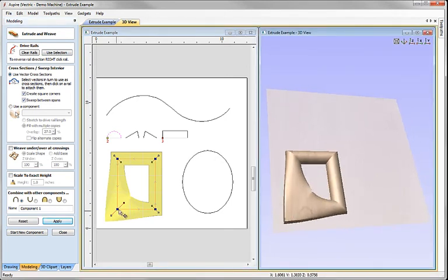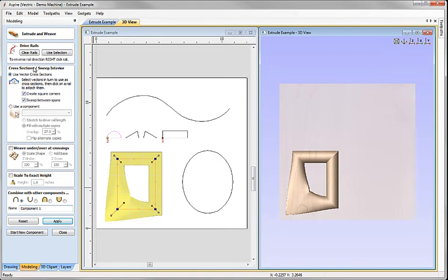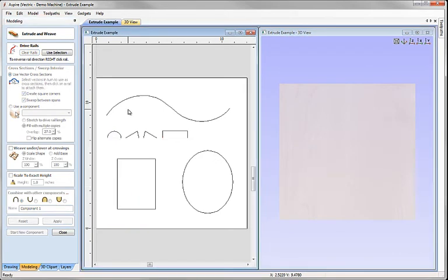So, as I say, you can't really replace the cross section on the start point, so if you do need to change that, then the best thing to do is always to clear your selection completely and start again by selecting your drive rail and going from there.